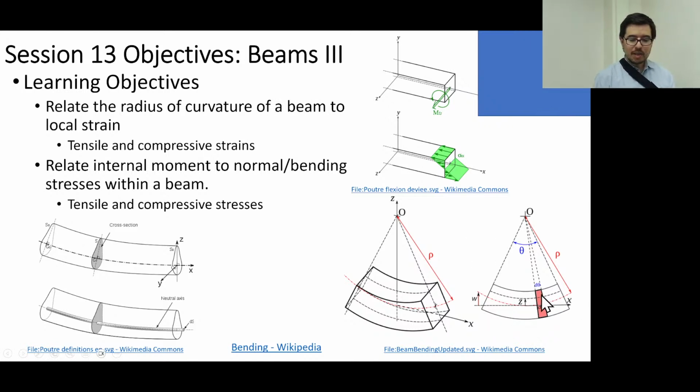Can you get an idea that, oh, the material here and here, they're getting closer to each other. So if I have a bend of radius like this, where the center of the radius of curvature is above the beam, that means that what is going on here? Is this tension or compression above? Compression. Right, and then look, if I go below, back down here, what's happening?